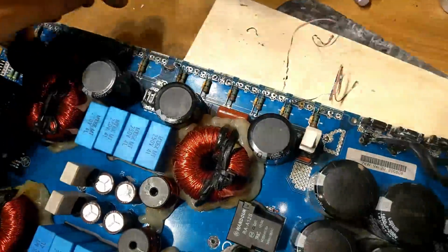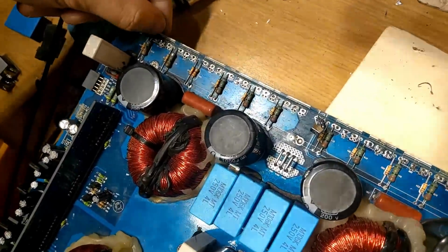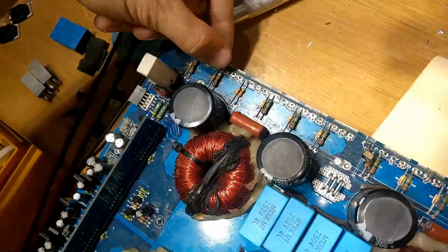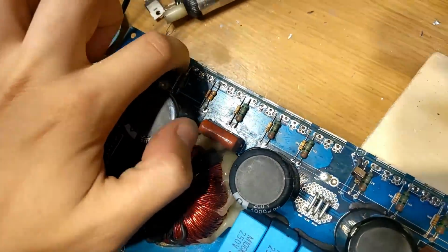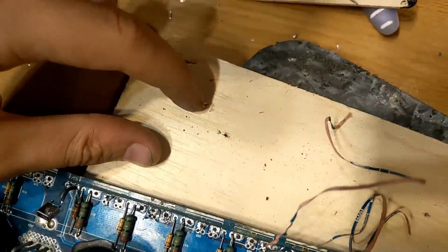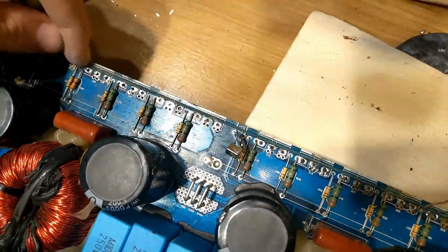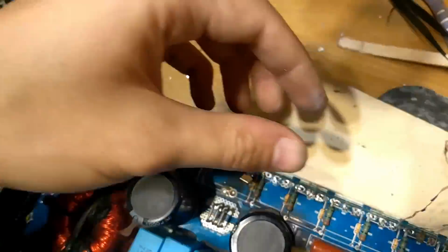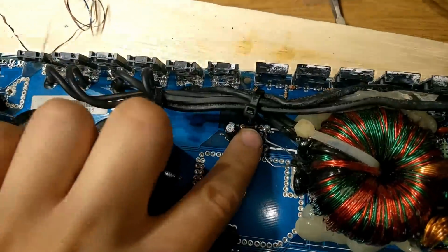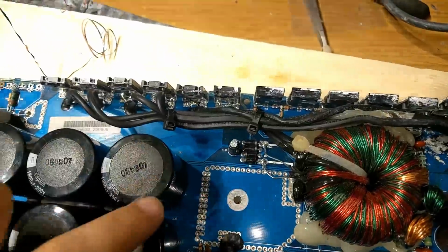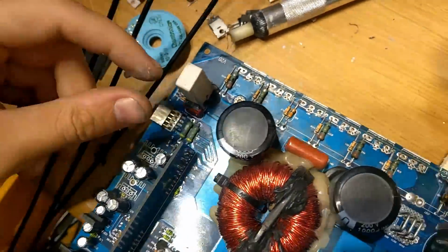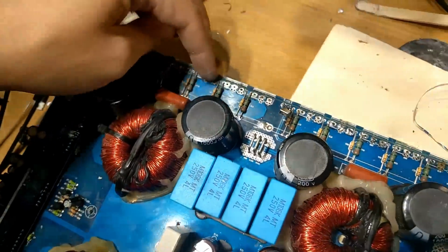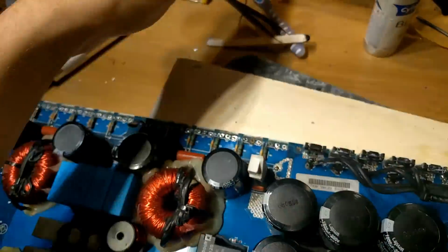This original trace that goes along the side here, rather than just take a tap of where it broke, because obviously when this happened, it completely obliterated a big section of the trace here. So there's a big hole in the trace where it was run. So what I did is I've pulled it all the way back to these rectifier diodes here, and I'm going to run a jumper trace underneath the board to get this 12 volt auxiliary up to the rectifiers without it having to pass by the FETs unnecessarily again. So that can go in the bin.